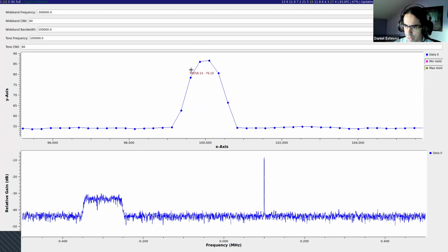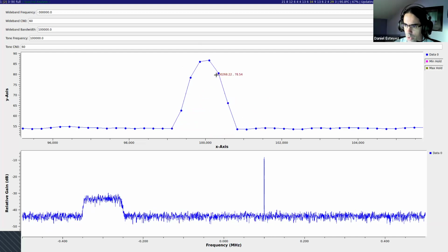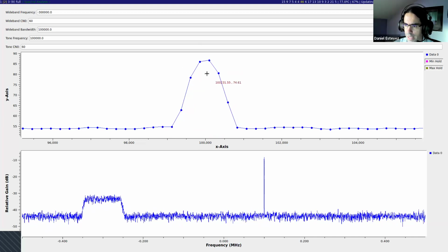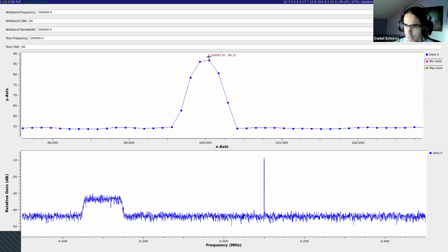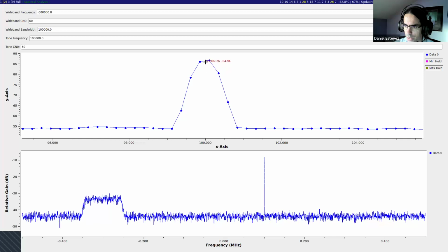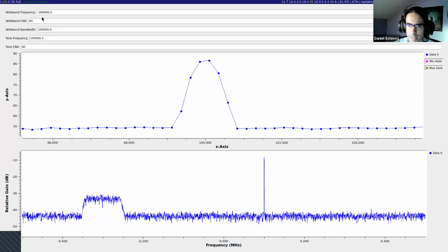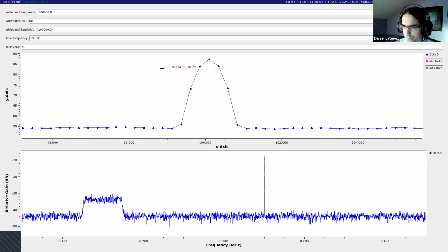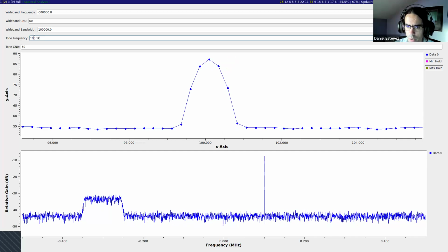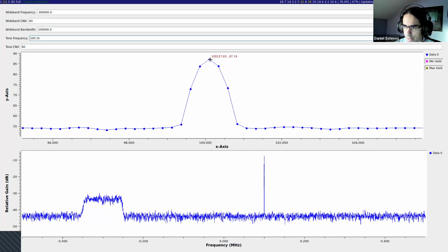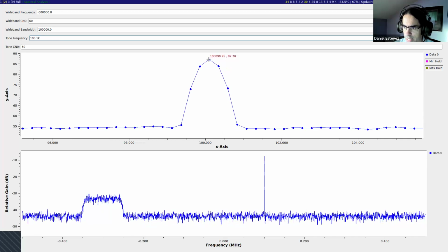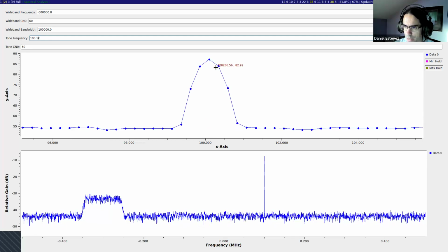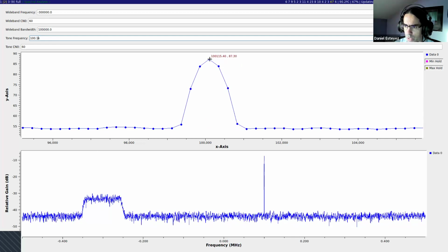But even so, if I look at these closely by putting dots in all the FFT bins, I see that my signal is in all of these. And also my signal is halfway between the FFT bins because they do not line up exactly with the signal frequency. I can play a little bit with this frequency. Let me try to see if I get it right. So now with 100 kilohertz point one, the signal is almost exactly in one of the FFT bins. You can see these two are the same height. So this is how I know the signal is well centered.